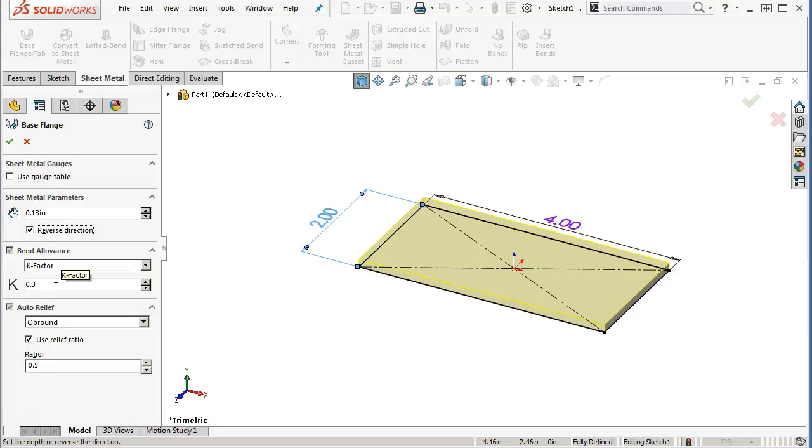0.5 is a good guess. Now, we're going to look at the other bend allowance settings. But think about just a piece of material sitting there on the table: whatever the internal stresses are this way are going to be the same this way. It's when we make that bend, and this radius grows and this one goes very tight, that we've upset that balance. So if it's in free state, would that be a K factor of 0?